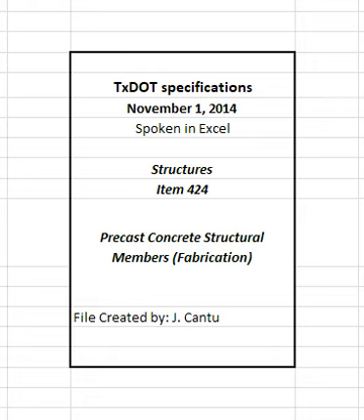4.2.2.2.4 Strand debonding. Encase strands in plastic sheathing along the entire debonded length, and seal the ends with waterproof tape when shown on the plans. Use split plastic sheathing only if the seam is sufficiently sealed with waterproof tape to prohibit grout infiltration. Do not use sheathing that will permanently alter the physical or chemical properties of the surrounding concrete. Full-length debonding of straight strands will be approved on an individual basis.